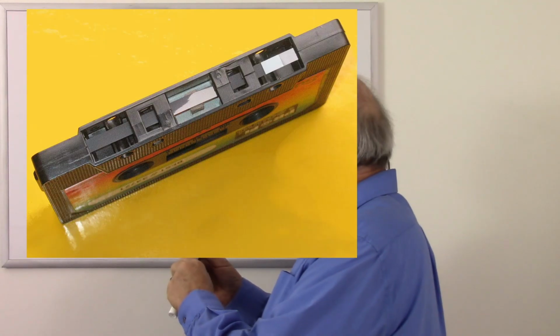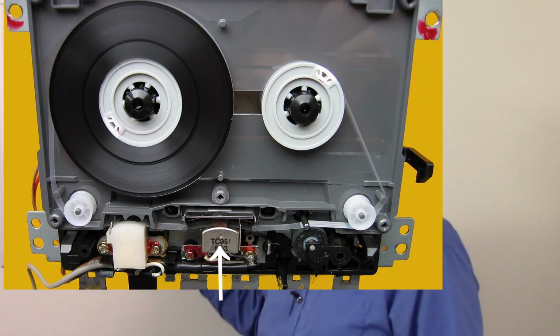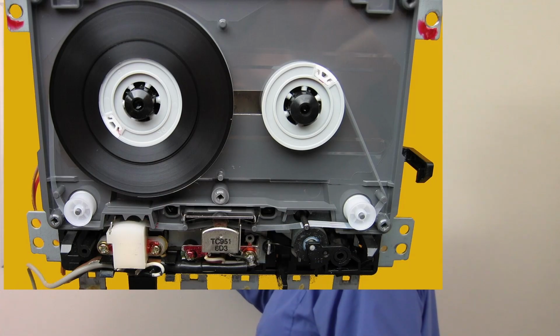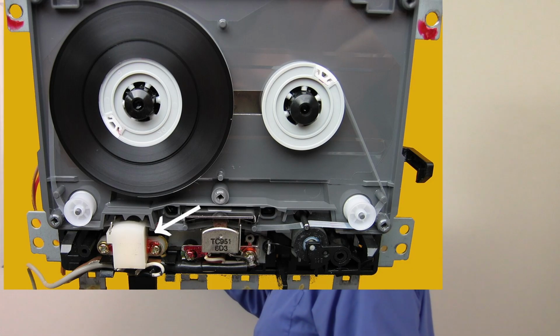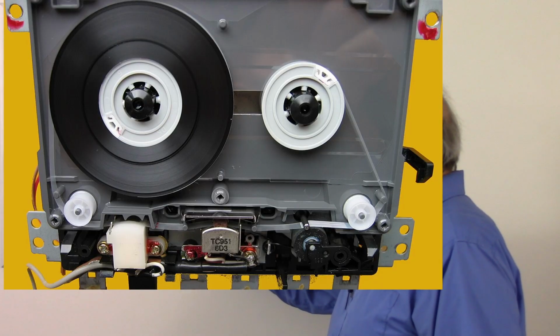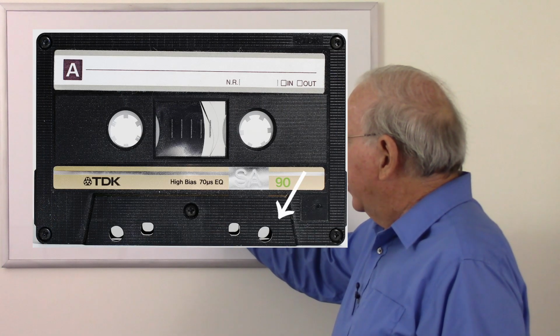So let's take a look at that from the top. So we have our head, and inside the cassette is a little pressure pad, so they did not use hyperbolic heads. And so there's a head, and then there was an erase head, so there are two heads, erase and playback. And over here there's a third window which would accommodate the pinch roller, and a little hole here to accommodate the capstan which came through that.